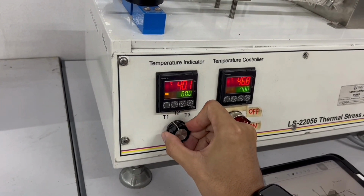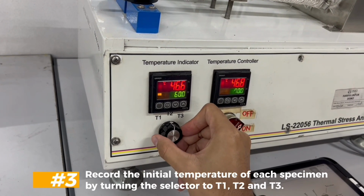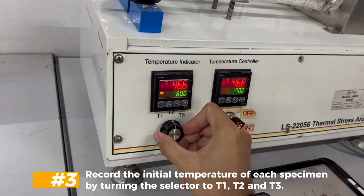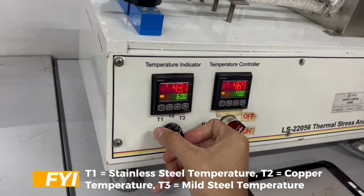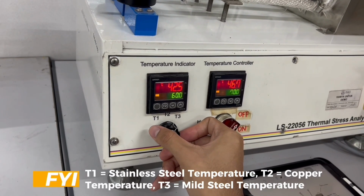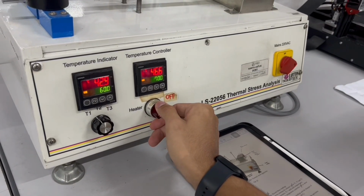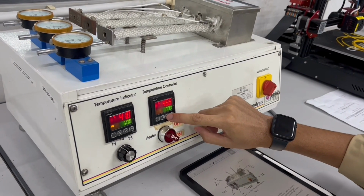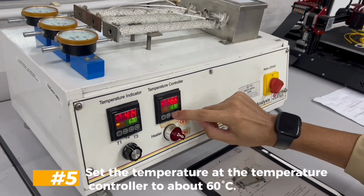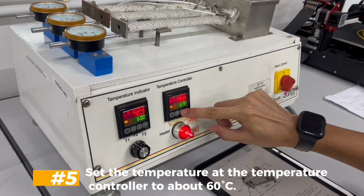After that, we need to record the initial temperature of each specimen by turning the selector to T1, T2, and T3. For your information, T1 is for stainless steel temperature, T2 is for copper temperature, and then the last one is T3 for the mild steel temperature. Next, to start this experiment, we need to switch on the heater. The next step is to set the temperature at the temperature controller to about 60 degrees Celsius.